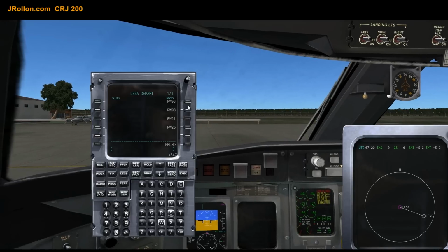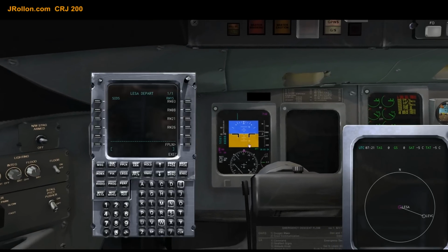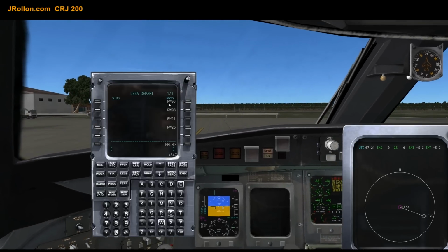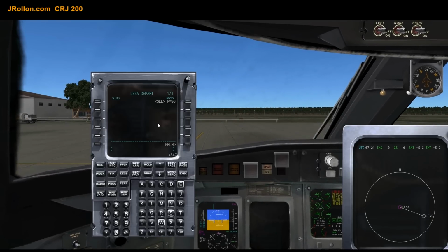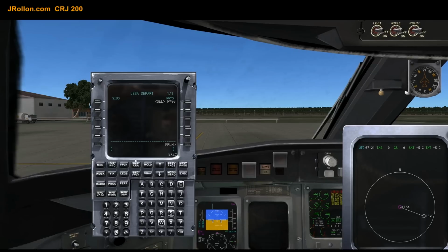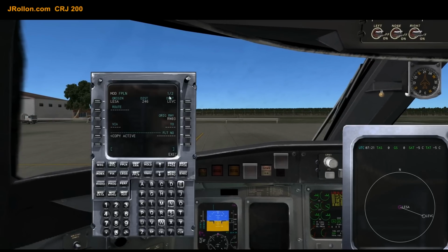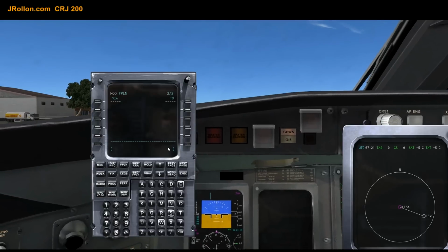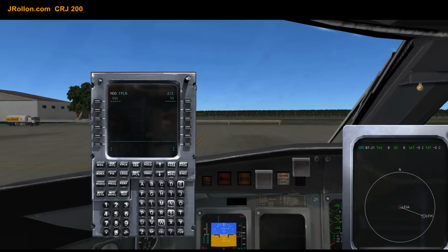We're going to start from the, you see how right now it has initialization, the primary flight display. So we are going to set this one, select, there is nothing to choose anymore, so no problem in that. So we are going to continue with the flight plan. We are right now on the 1, 2 page, so we press next page. And the first thing we are going to do is go direct to UNSOL. So we type UNSOL,